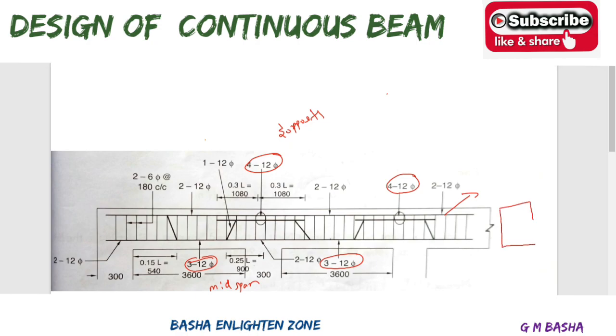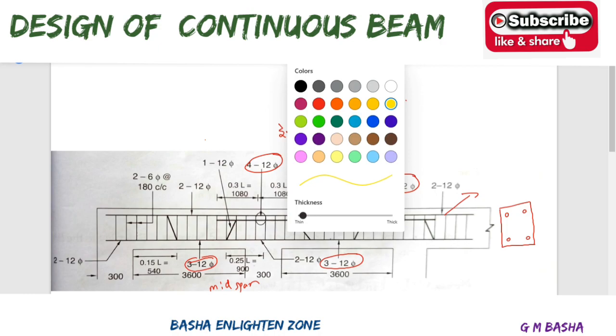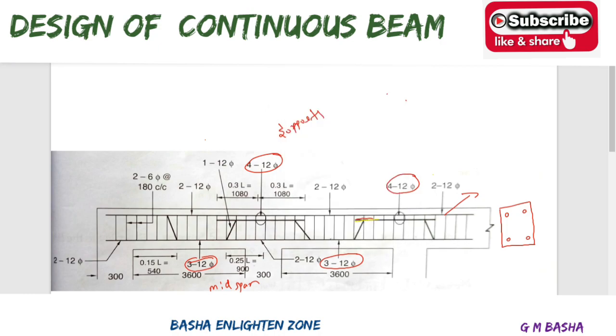If you cut this section, what happens? The top 2 bars will be here, and the bottom 2 bars will be here. One will be here, 2 bars will be here. And again 2 bars will be required at the supports. So one straight bar is provided like this. I will mark it with a different color, yellow. See here, there will be one more bar from here to here, and here also from here to here, and that bar is provided here, that is the third bar at the supports.